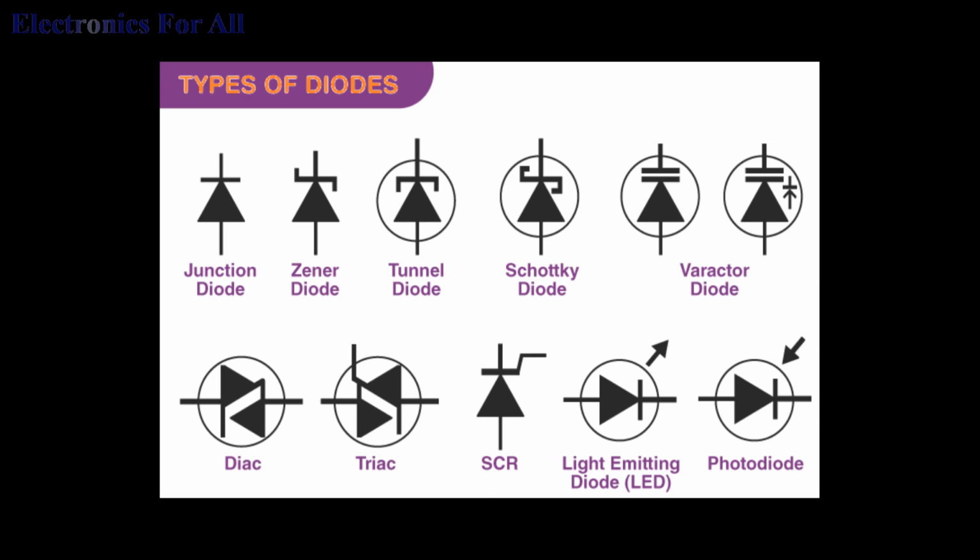When the diode is in on mode, no voltage is there across it, hence it acts like a short circuit. 2. Whereas when the diode is in off mode, there is zero current, hence it behaves like an open circuit. 3. From the above two conditions, either one can take place at a time. This helps us to check out what will happen in any circuit with diodes.